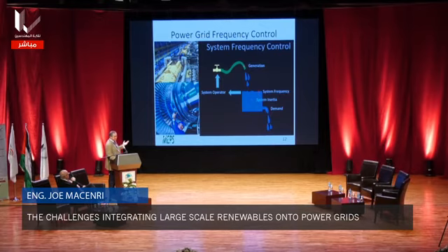Okay? Now the advantage of that kinetic energy is it helps with the system frequency control. Here's showing an analogy that you have generation going into a reservoir and you have demand coming out of it. The bigger that reservoir, the less the level in that reservoir will change if there's any change to the generation or any change to the demand. The smaller that container becomes, the more that level will move up and down. Ireland has studied this, and I'll show shortly why. Ireland is ahead of the curve in terms of having to deal with these issues.